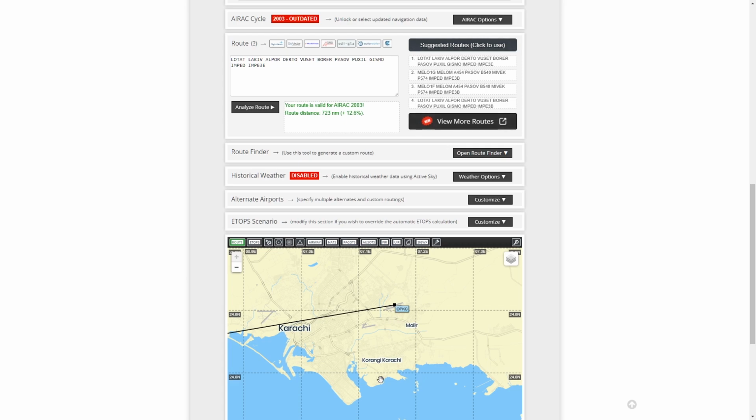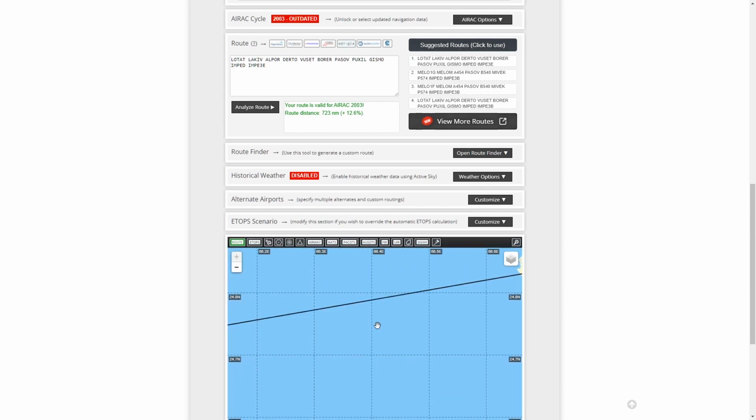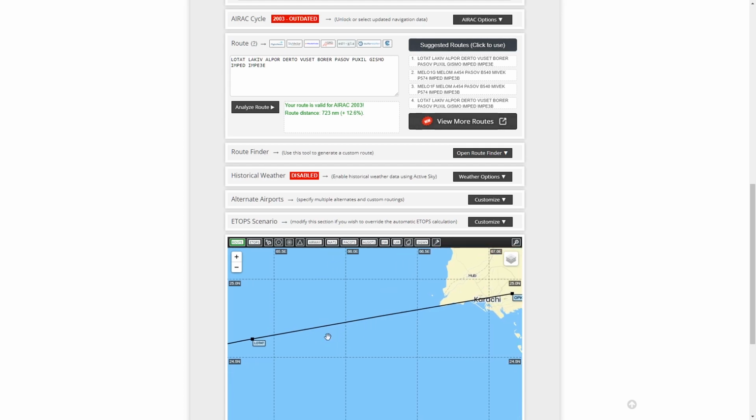In the flight planning, there are two things. Remember, it's a SID and a STAR. SID is a standard instrument departure, and STAR is standard arrival for the instrument, for the flight plan. So your flight plan should have proper SID and STAR for the departure and for the arrival. Right now, you can see that for the departure, the procedure is not normal. It's just a dot over here and a straight line going on to a certain waypoint in the flight plan.